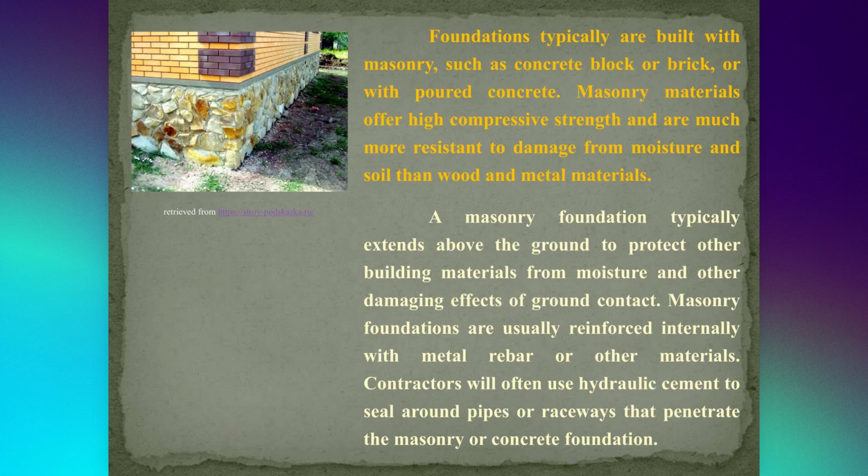Foundations typically are built with masonry, such as concrete block or brick, or with poured concrete. Masonry materials offer high compressive strength and are much more resistant to damage from moisture and soil than wood and metal materials. A masonry foundation typically extends above the ground to protect other building materials from moisture and other damaging effects of ground contact.